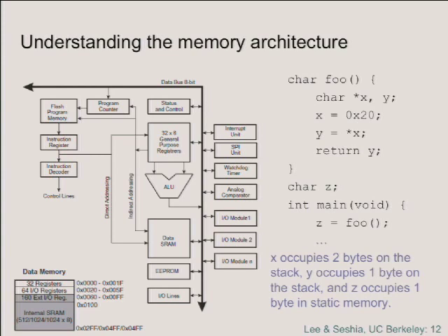Yeah, question. So in this architecture, what's your name? Nima. How do we characterize integers? Because our bus is only 8 bits, so if you have an integer, how does it work? Well, one of the glories of C is that it doesn't actually define what an int is. So it's up to the compiler to decide what to do for this architecture.